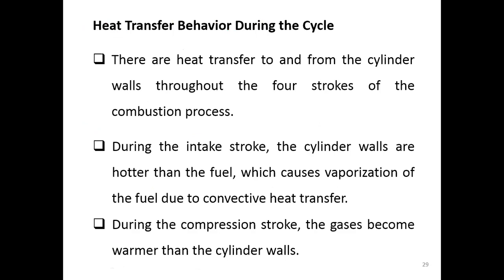So this is the problem that we face when we do the heat transfer analysis. Some fluid, the gas inside, changes. Another fluid, the coolant outside, is constant. The wall is constant. So the heat transfer has to happen under these conditions. So we look at how the heat transfer behaves during the cycle. There is heat transfer to and from the cylinder wall throughout the four strokes of the combustion process.